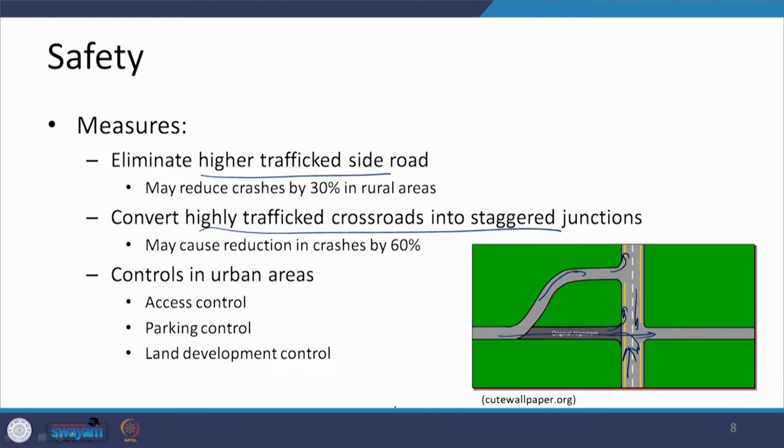So, the left turning has been brought at this location, and then there is a straight, that means that we are going for a staggered condition. So, we are going right and then left, and that is how the type of conflict has been reduced here, and there are no such conflicts otherwise at this one, other than this traffic which is taking a turn here. So, this one conflict can be there.